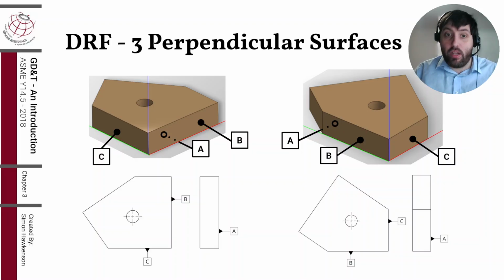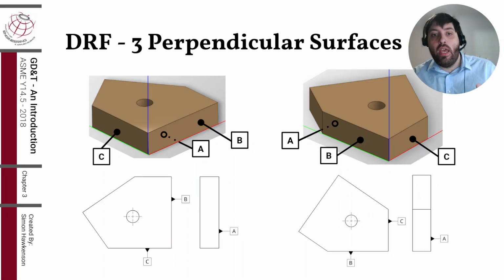That's the important part. The surfaces themselves aren't perfect, of course. You can't have perfect surfaces. So they aren't the datums themselves. That's why we call them datum features. They sit along the datum.